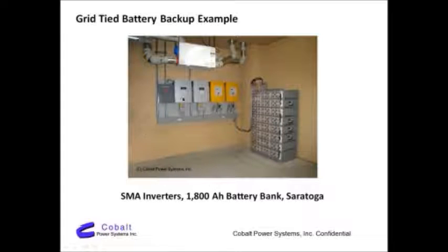And by the way, what you're looking at here is an inverter. This is an example of a different type of system called a battery backup PV system. It does everything that a grid-tied system does. It'll spin the meter backwards, it'll sell to the grid, it'll have environmental benefit and financial benefit, which we'll talk more about towards the end. But in addition, when the grid goes down, it will take power from a standby battery, which is right here. This is a larger type of battery at 48 volts, and that power will be used by these two separate inverters, converted to 240 volts AC, and power the home.